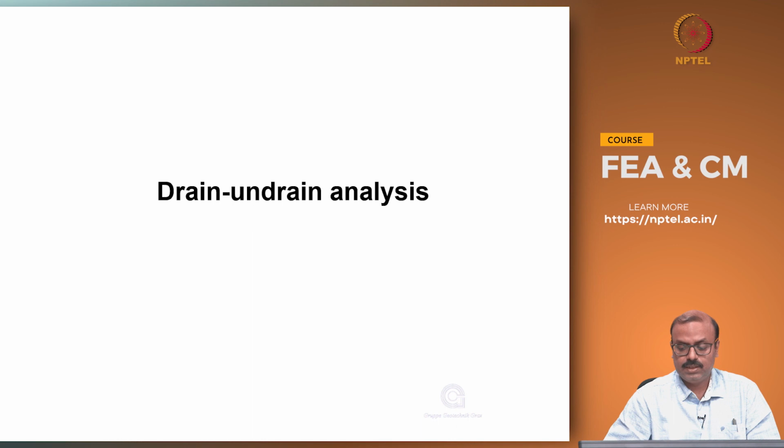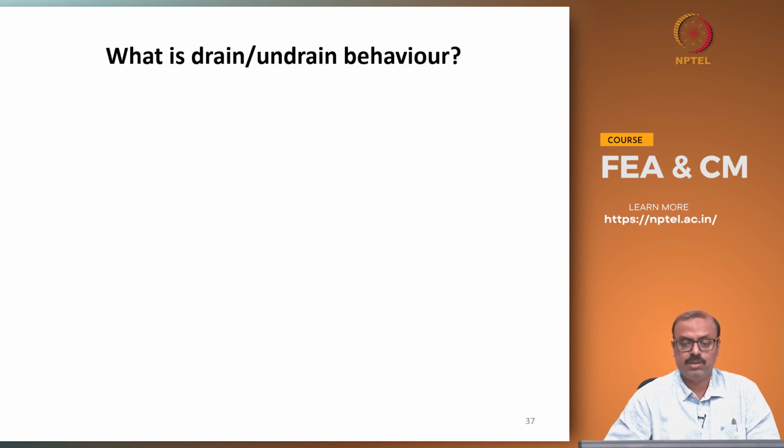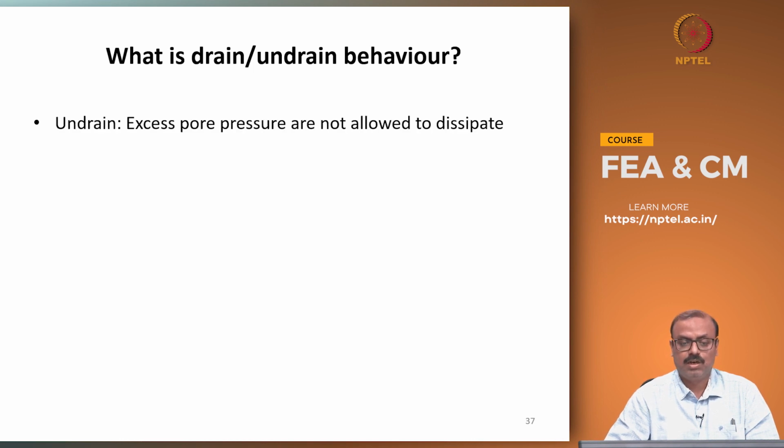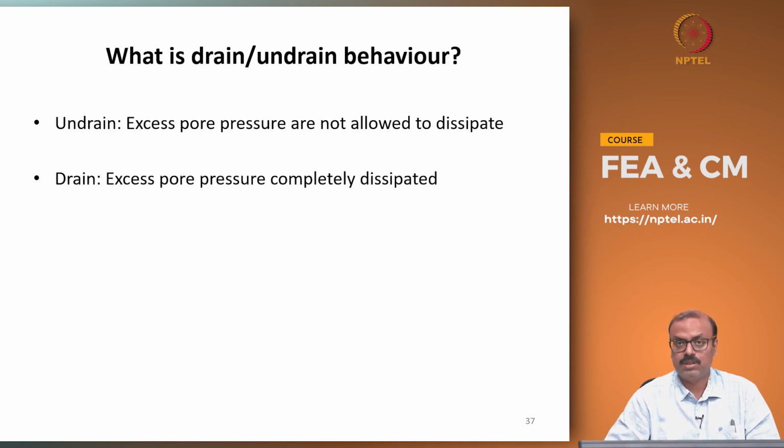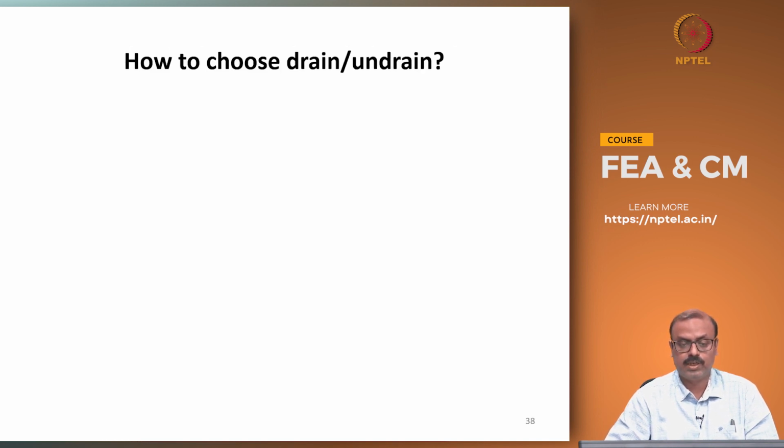Now, as I said, one of the major issues is the type of analysis, whether drained or undrained. So, what is drained and undrained behavior? I know that this course has been discussing drained and undrained quite a number of times. So, we will just see how software treats it. Before going into that, in undrained, generally excess pore pressures are not allowed to dissipate, as we all know. In drained, excess pore pressure is completely dissipated. That is the simple way of looking at it.